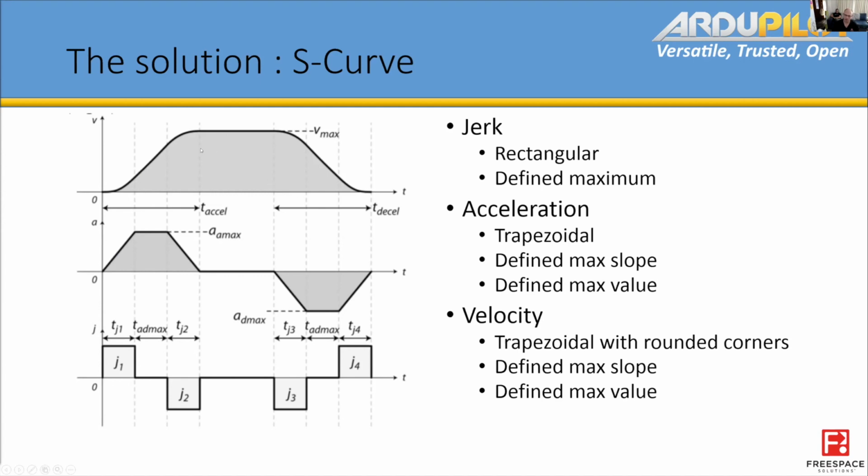Now, when you realize that in a multi-rotor or a helicopter, this acceleration is our lean angle, and this is our rate of change of lean angle, you can see a problem here: we have an instantaneous angular rate of change, or angular acceleration, as we go to initiate a movement. Now, this is the dreaded twitch that we talked about.